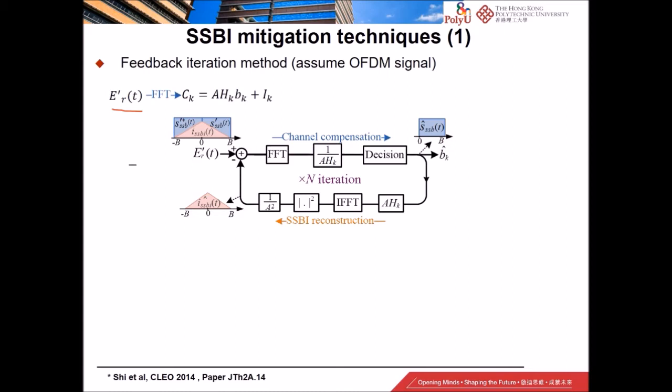is the spectral component at frequency index k. Okay, it consists of the following: the original signal, and then the channel transfer function, and then the noise. Okay, and then the A again is the DC carrier, DC signal. So then what we can do is we first cancel out, divide by A and H. Okay, make a decision here about the transmitted bit B.